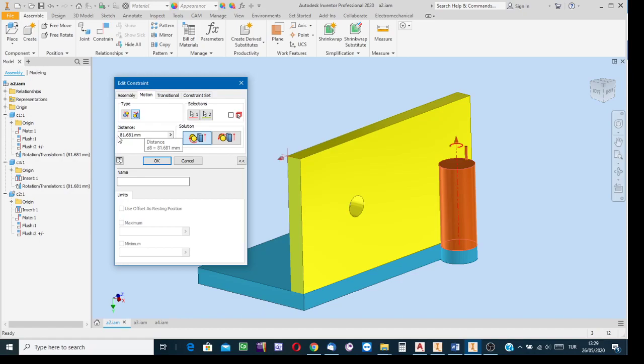Well, the value 81.681. What is that? If there is no slippage between the surfaces, because there is a tight connection between them, the friction force has not been exceeded yet. So the maximum value of the friction is the dry friction coefficient times the normal component of the force, acting at the mating surface, action and reaction.